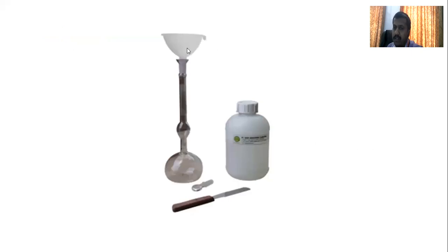The same way as we use the specific gravity bottle in determining the specific gravity of the sand by using pycnometer, now we are going to take 4 weights. At first the empty weight of the bottle, then the partially filled weight of your specific gravity bottle with the cement.